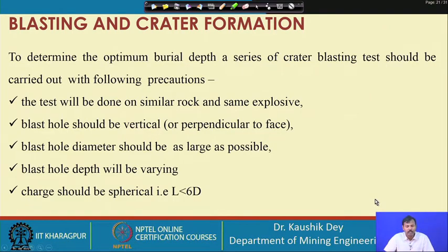So, to determine the optimum burial depth, a series of crater blasting tests should be carried out with the following precautions. The test will be done on similar rock and the same explosive must be used, because we want to know the rock explosive interaction between two things, one explosive and one rock. So, that is why the experimentation must be carried out on similar rock. It is better to use the same bench, and we should not change the explosive during our experimentation. Blast holes must be vertical, so that they are perpendicular to the surface.